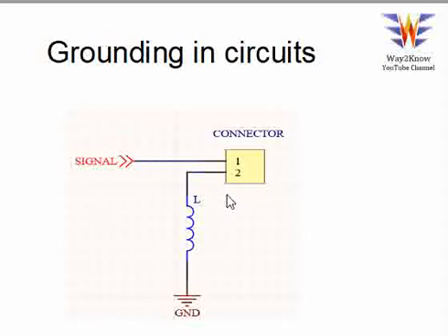Now, how does the inductor also help us? Let us assume you have AC power to your circuits or something, and then you have another connector where you are going to combine these cables. In those scenarios, you should not have the blockage of 50 to 60 hertz signals. They should pass by without any issues. So in that scenario, again, this inductor helps, and high frequency noise is being blocked.